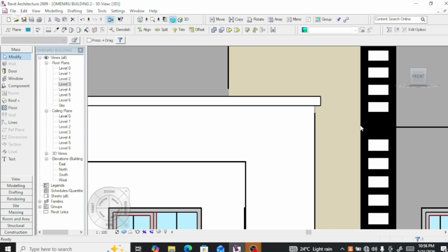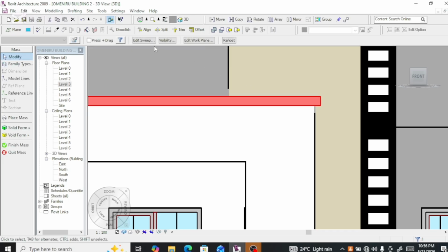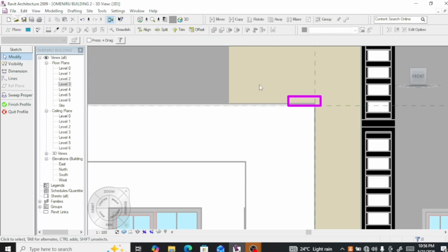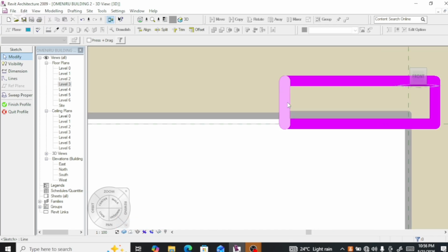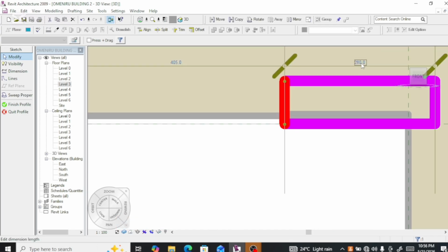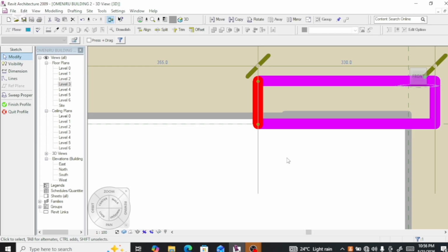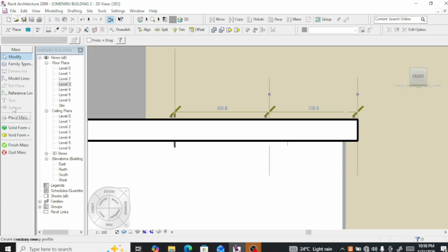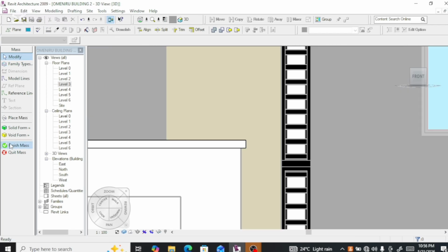Highlight, my cardinal is here, which is my pivot point is here. Okay, highlight it. Okay, edit. This is it. I just come here, just add 30. This one is 50, right? Plus 30 here should plus 50 as well. Should give me 330. Should achieve this. It's inside as well with 50 millimeter.